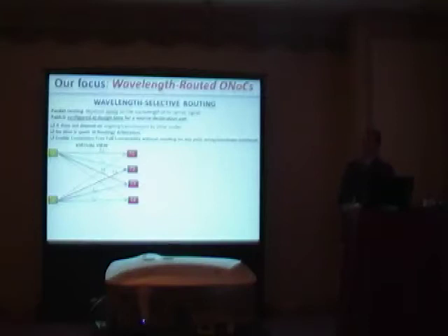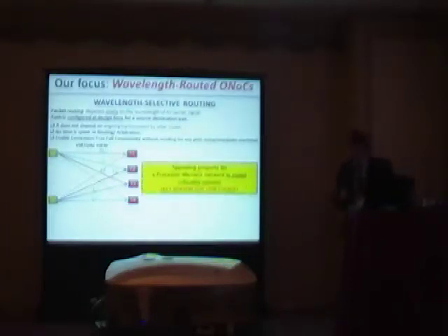This kind of optical network relies on the principle of wavelength-selective routing. As you can see here, if the initiator I1 wants to communicate with 4 different targets, T1, T2, T3, and T4, this is possible by using 4 different wavelengths, λ1, λ2, λ3, and λ4 respectively. Notice that no time is spent in routing and arbitration functionality, and this kind of network enables contention-free connectivity without needing any path setup or teardown overhead. Certainly, this is an appealing property for processor-memory networks and mixed-criticality systems.